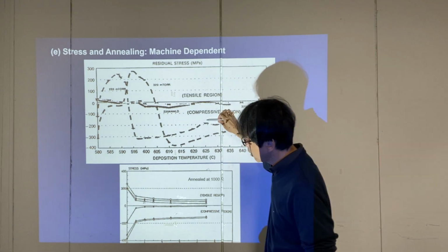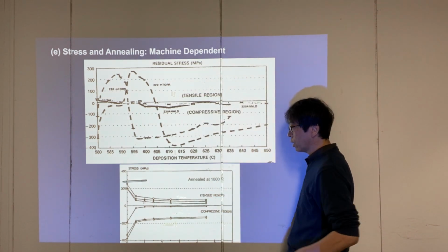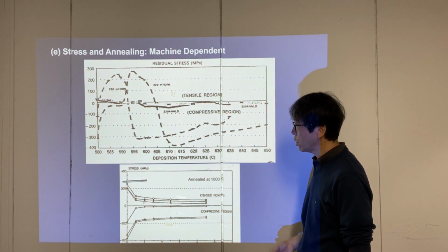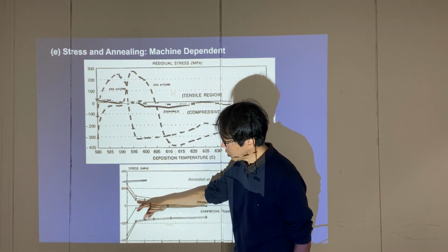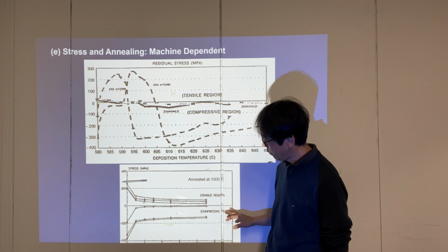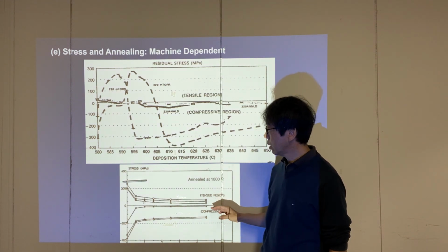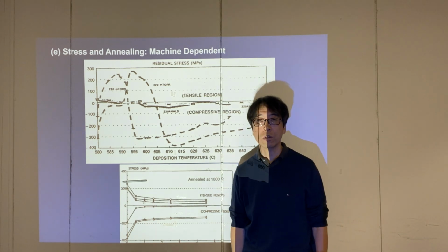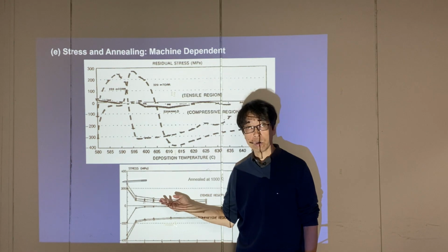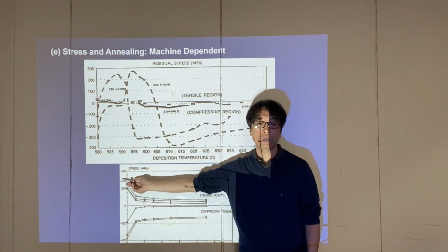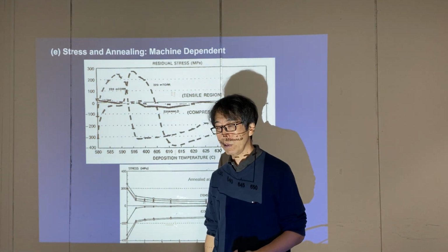In case you obtain tensile silicon, that's why we need annealing again. Through this annealing process, we can lower the built-in stress as a function of time. If you leave your wafer at a high temperature, 1000 degrees Celsius, for long enough, you can obtain lower stress structures. That's where we need annealing. There are a number of different reasons why you need annealing.